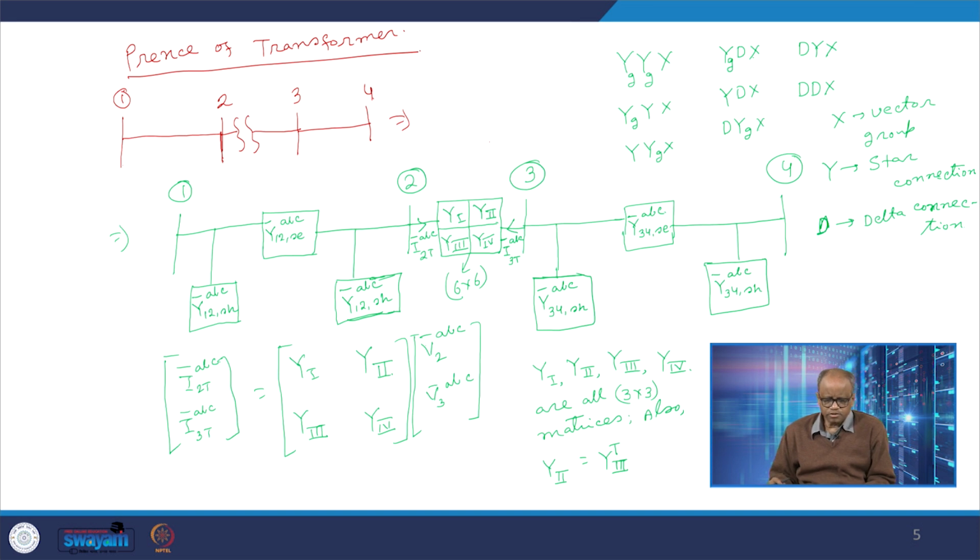We also have seen that this x value would be 1, 3, 5, 7, 9, 11, that is essentially the odd numbers, if the two sides are of different type of connection, that is, if one side is Y and another side is D.